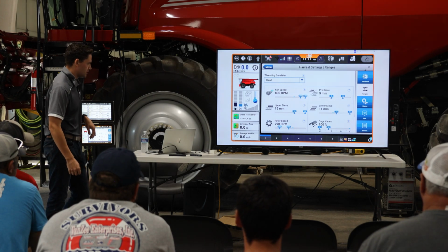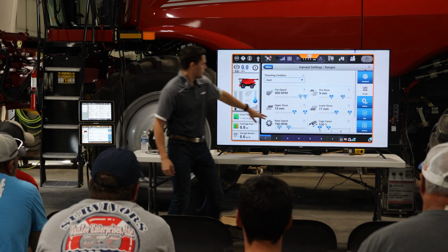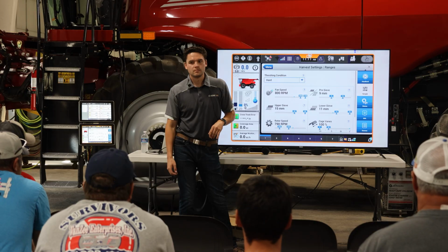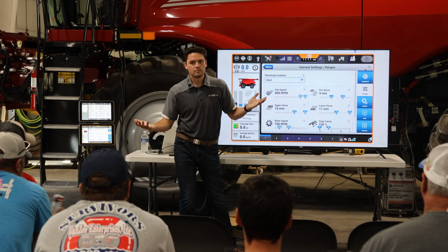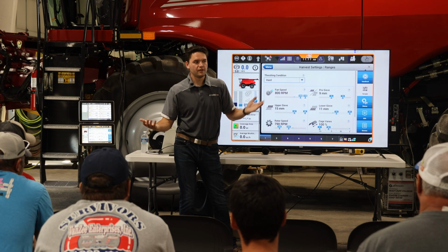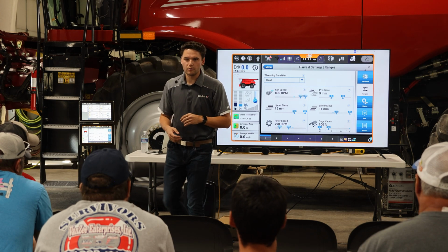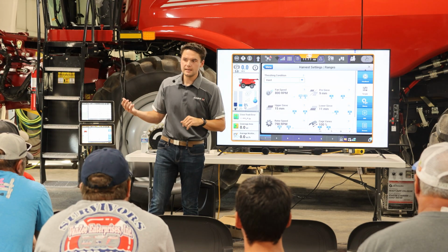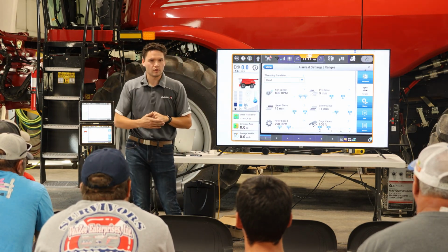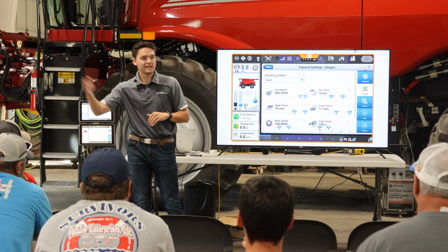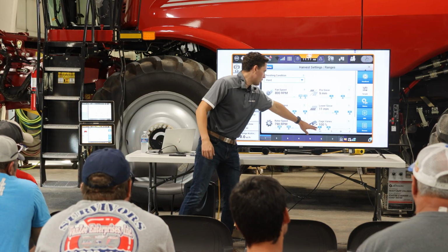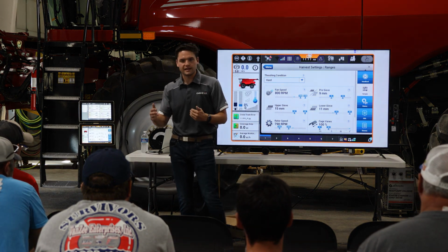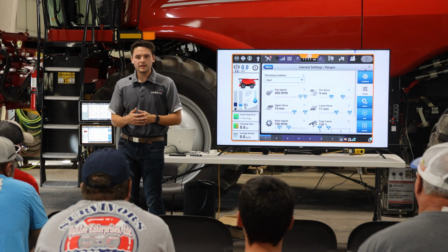Maybe I adjusted my rotor speed, that's what I did wrong. But what happened with my K pins? So now, if it could go 80 to 0 before, where 0 is the most amount of threshing passes, and 80 is 80% speed, so it's almost as fast as it can go. So less threshing passes, it can now go the most or 30%. That's 50% less.